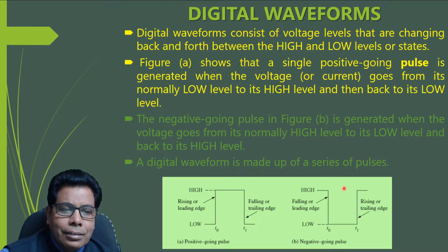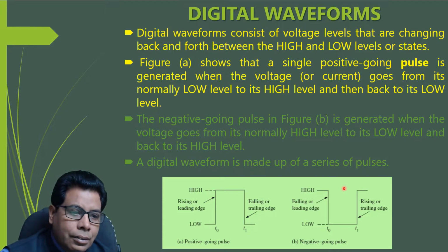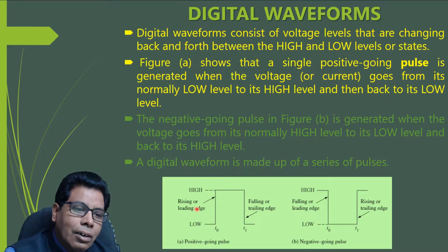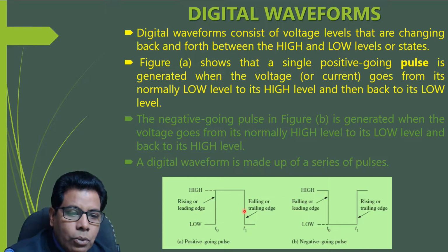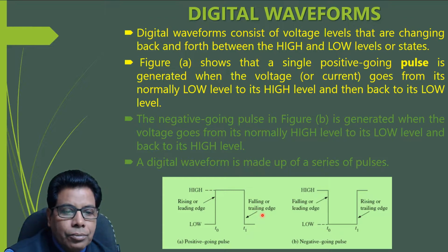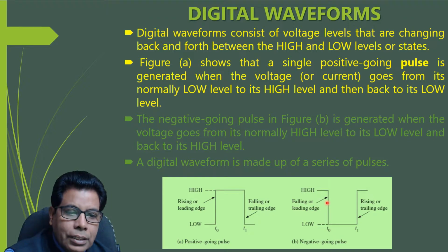Now here you can see the rising or leading edge. When it is going from low to high, we call it the rising or leading edge. When it is going from high to low, we call it the falling or trailing edge. Similarly here, it will have the falling edge on this side, and the rising edge on this side.